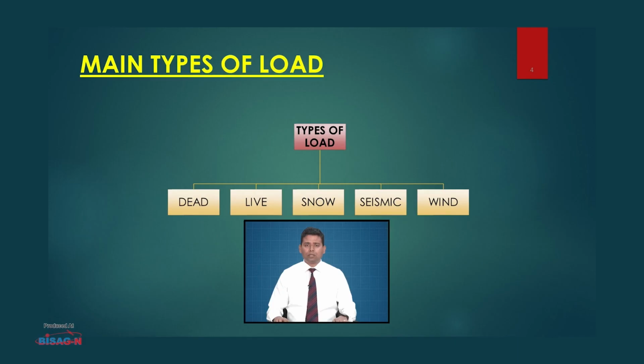Now, let's focus on the structural safety of the building. It is governed by various design loads to which the building is exposed or likely to be exposed. Various types of design loads which are to be considered are dead load, imposed load, also referred as live load, wind load, snow load and seismic load.